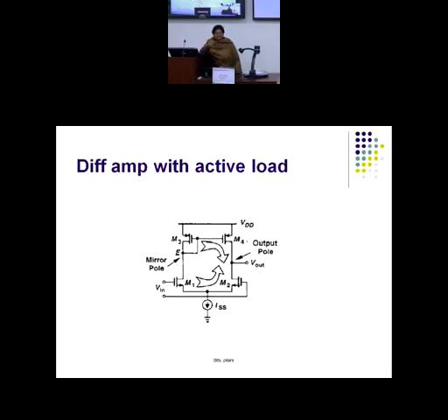And remember, in an IC, the pins which are going outside the IC packaging, they go to it through a pad. So there is a huge capacitance at the input pad. Now the pin which comes out, there you apply your input signal. Remember, you must have worked with any IC. You give your input AC signal, your function generator is connected to the input pin. Clear? So in that situation, what will be the omega in?